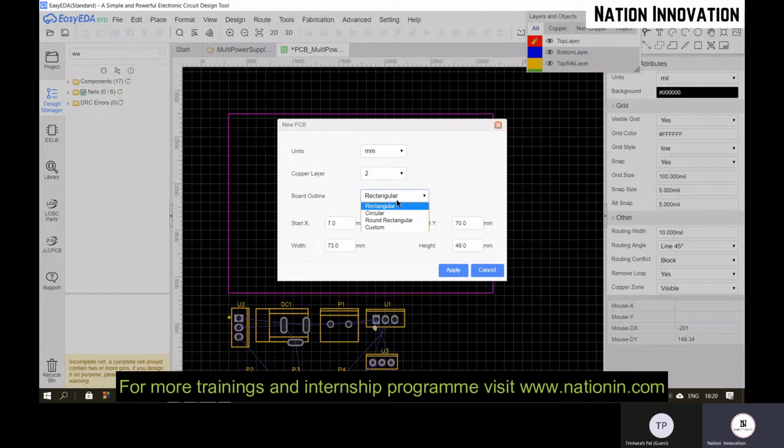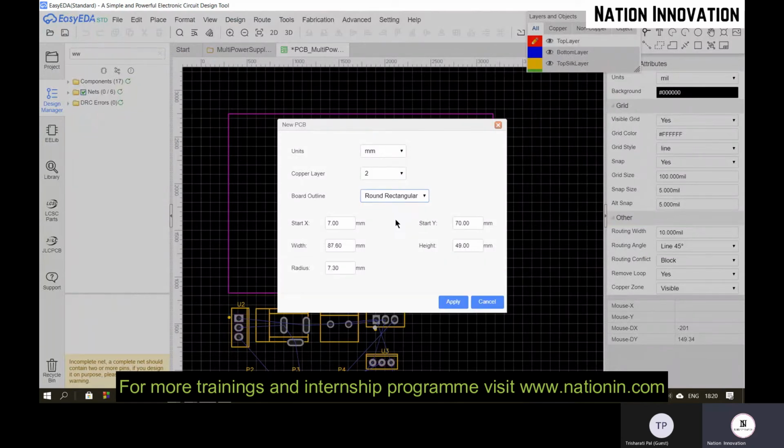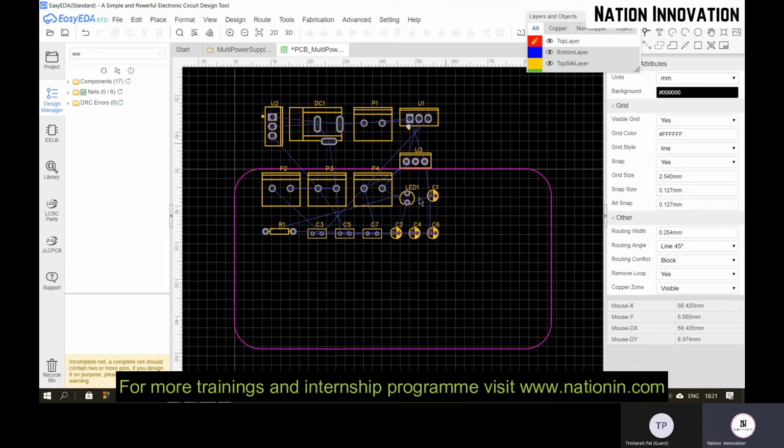And let me make it as round rectangle. And starting point is again 0, 0. Let the width and height be same now. We can change according to our requirements later. So press K to fit the window.